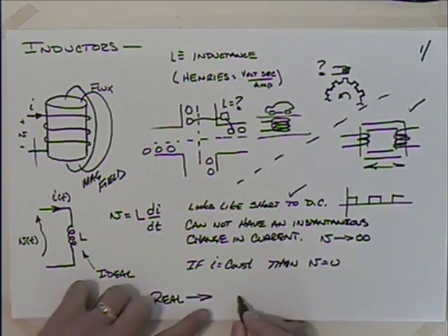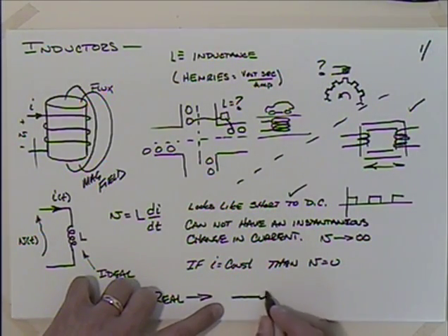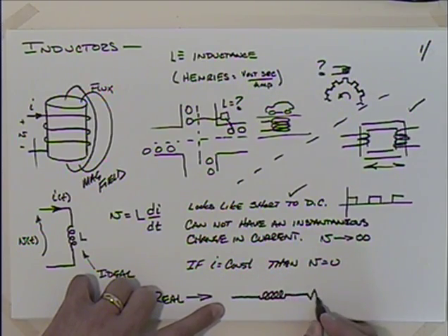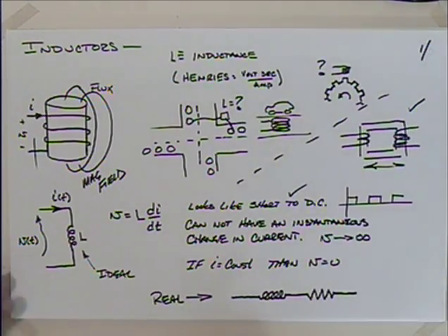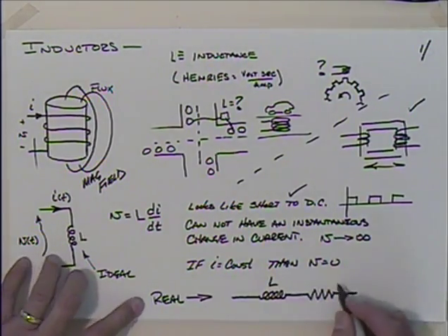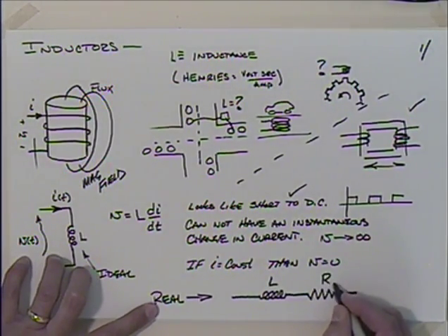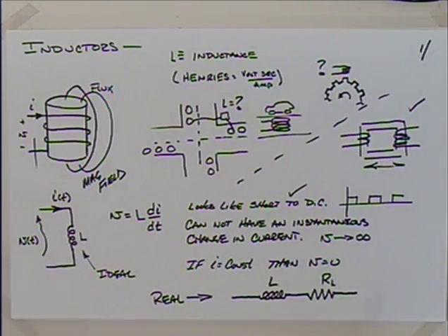more real-life inductor, it looks like what? Well, there's going to be some inductive portion, and then I'll try and make good schematics there. So there's the inductor with the loops, and there's the resistor. We don't want the loops. So your inductor here, and it's going to have a lot of resistance. We'll sometimes call that R sub L. That's the internal resistance of the inductor.